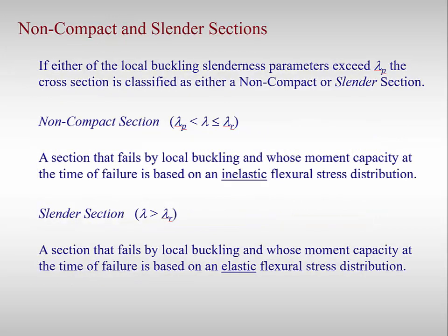Sections that are not compact are classified as either non-compact or slender sections. Note that non-compact sections have an inelastic stress distribution at the time of failure, and slender sections have an elastic stress distribution at the time of failure. This class will focus on compact sections.